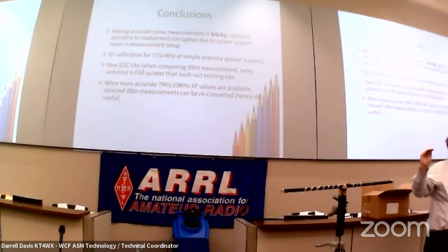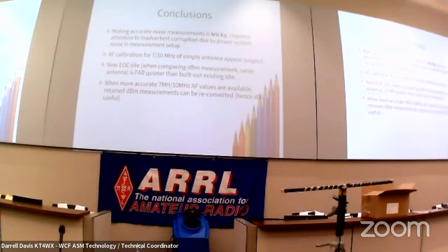And so then we could say, well, if you had met Class B standards, home standards, it would have been okay. If you had exceeded Class B standards at this frequency by 5 dB or whatever, it would have been okay. So we are able to take those measurements and tell the manufacturer, you not only have to say that you meet Class B standards, when we install it, it needs to meet Class B or exceed Class B by this amount. And if it does that, we should be okay. Class A, you're going to have to exceed by a good bit because Class A is industrial standards and they're a lot looser. But we did that measurement.